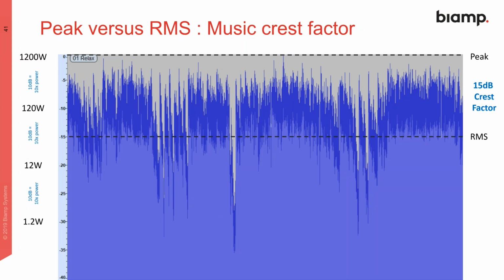So you can see how the program material can dictate what your RMS power out of your amplifier is going to be. The RMS power matters because that's going to be your average duty cycle for the amplifier. What can you maintain? And the TesiraXEL, we've got very good results with testing on our power supplies, and so we really don't have any caveats in terms of program material. We won't sustain a 1200 watt sine wave indefinitely, but with program material, you're going to be able to play a program all day.